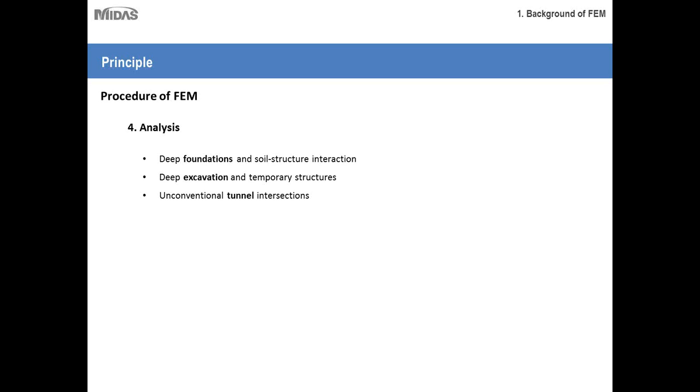Then we have to move on and perform the analysis to solve the equations. So finite element method is found very helpful for the following types of analysis, such as deep foundations, where you definitely need soil structure interaction, then deep excavations, where you need to analyze the forces in temporary structures, then unconventional tunnel intersections, where you have to see the stresses as well as displacement in the connecting galleries or the connecting points or the junction points,